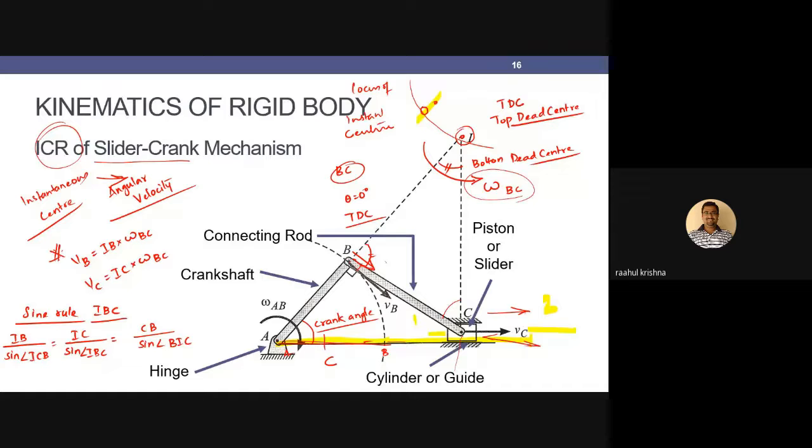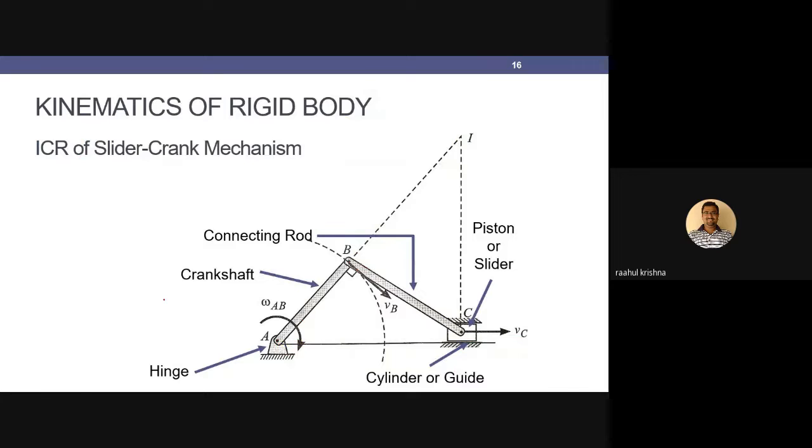After I get this, when I have one question, let us start. Let me erase all of them. So when I have one question, firstly, in the graphical method, I'll be drawing this. I'll make the perpendicular from one end of the link, then the perpendicular from the other end of the link.